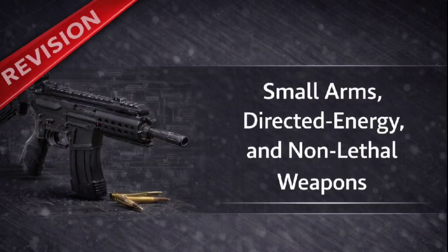1/16. That is incredible. And the final variation is the most complex hybrid, blowback with a locked breech. This system temporarily locks the breech physically, just like a recoil or gas system would during that high-pressure phase. But instead of being unlocked mechanically, Let me guess, the gas does it. The breech is deliberately unlocked by the residual gas pressure itself, causing it to blow back and cycle. That sounds complicated. It is. While this allows for the lightest possible breech block with high-powered rounds, it's extremely complex to manufacture, and it's notoriously sensitive to tiny variations in ammunition quality. The unlocking timing is just so fine.